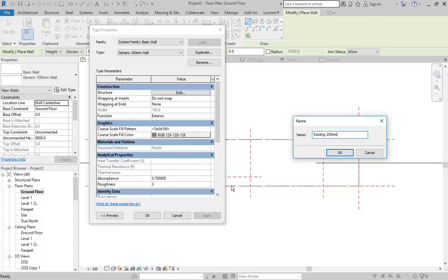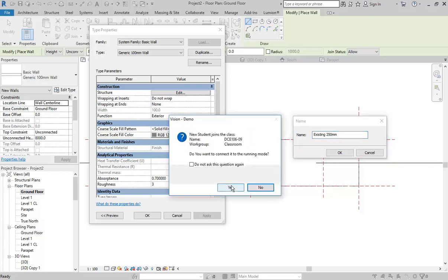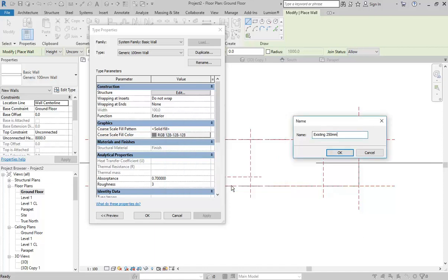But that's a real giveaway. If you see a thickness like that, you can generally assume it's solid brickwork, so no cavity, and that means it is 110, then 10 mil mortar in between, 110 again, and then 10 mil of render either side. That gives you 250. So 30 mil of mortar all up. That takes it back to 220 and then 2 bricks. So that's your 250. Anyhow, it's always interesting to look at that. Whenever you're drawing an old building, you can usually tell almost instantly whether it's from the middle of the 19th century or the end of the 19th century just from the wall thickness.